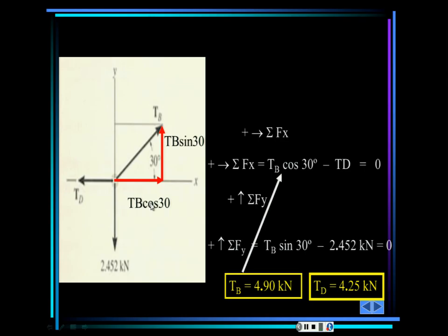That also means that the maximum number of unknown forces we can have at this statics level is only 2. You can't immediately solve a problem with 3 unknowns because we don't have the tools. When that happens, you have to use compatibility equations, which hopefully you will start learning in mechanics of materials, or mechanics of deformable bodies.